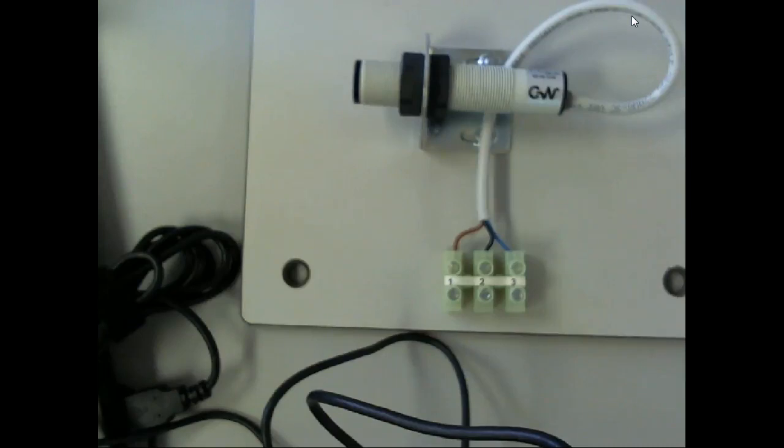Oh yeah, that's what they do. They usually trigger stuff. Most of these guys, we can use them for what we call proximity. So when we talk about proximity sensors, these are going to be your solid state sensors. Limit switches, even though they sense proximity, have their own name. So we have limit switches, and when we use the term proximity sensor, we're talking about a solid state sensor. And these are what we call non-contact sensors.